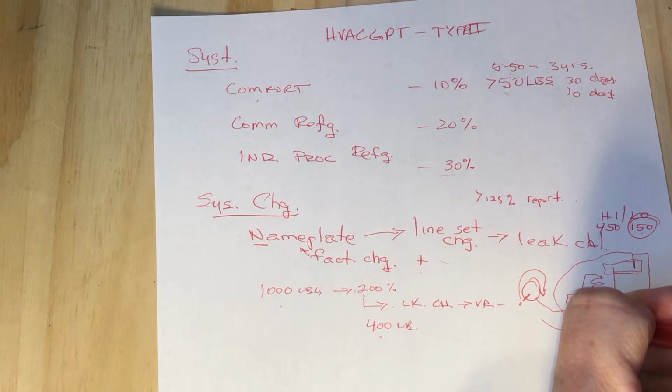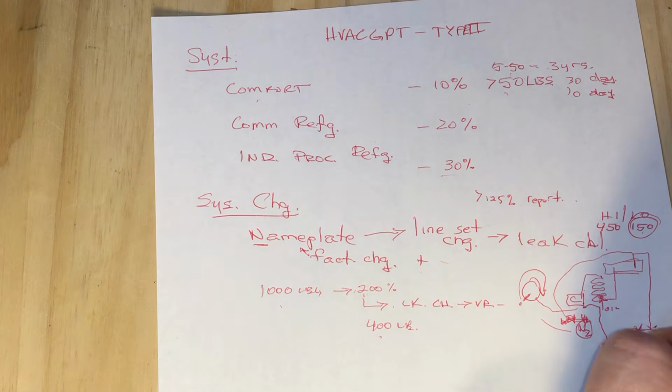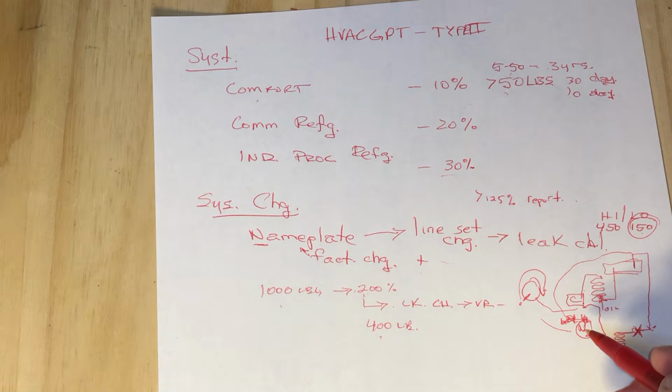So the regulator would be installed, and you would also make sure that you can't put 2 or more regulators in series. There's a flow guard, a flow meter that we put in for the brazing while we're purging and brazing. But other than that, there's only one regulator, and if it's got a pressure relief valve, those aren't installed in series, and they have corrosion. We replace those pressure relief valves on those regulators for those nitrogen tanks.